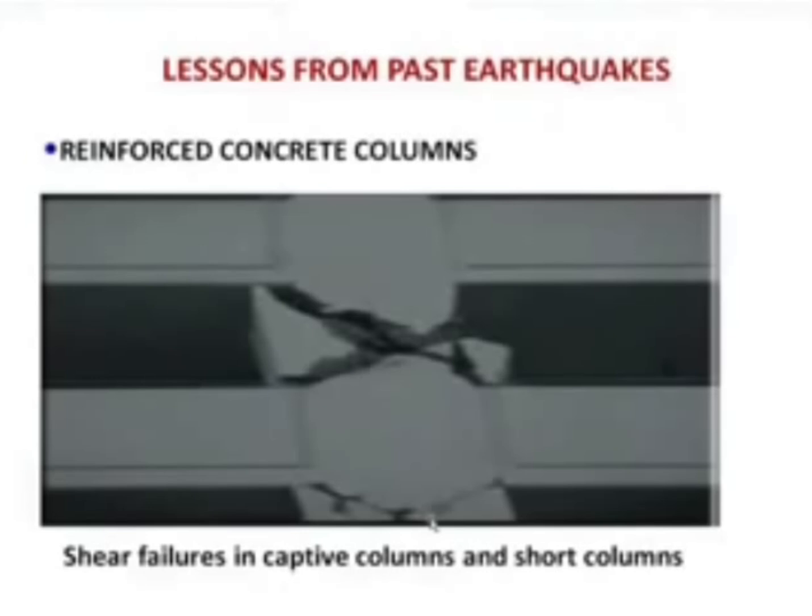L cube, that means if the L is less, then the stiffness will be very high. And if the stiffness is very high, then what will happen? That high stiffness zone will attract more forces. Naturally, when the more forces will be transferred in that high stiffness zone, and if the high stiffness zone is not designed for that force or moment, then it will collapse.